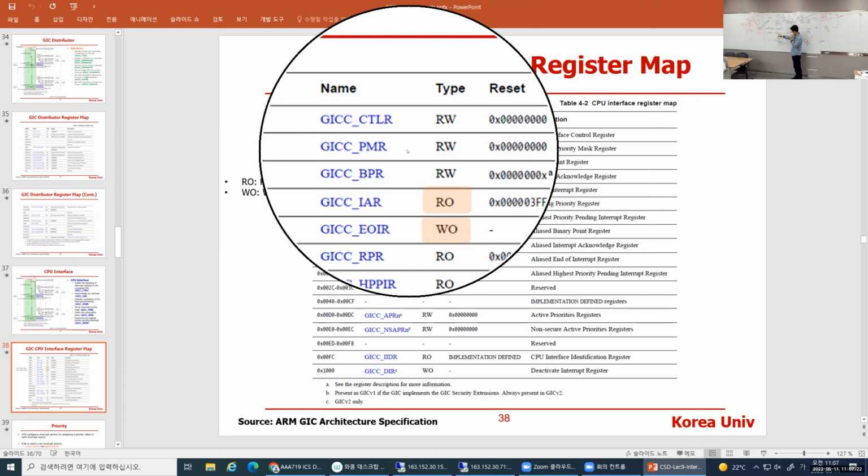And then let's say GPIO priority is 30 priority. And that will be compared against the threshold 20. It turns out that this priority is lower than this threshold. That means the CPU interface will not forward the interrupt. Ignore the interrupt, will not forward to the CPU.